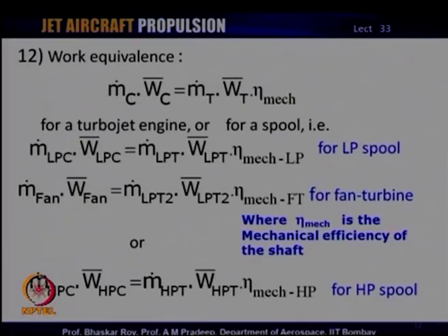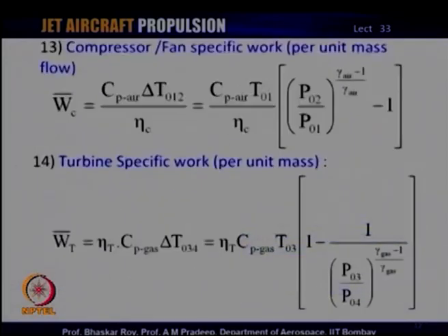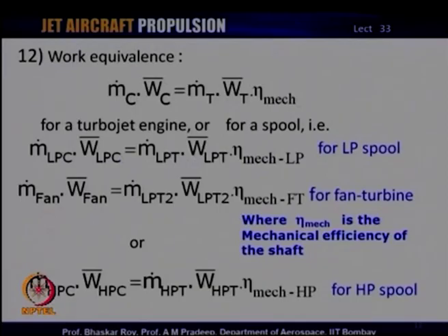Now, all the spools are having matched work between the turbine and the compressor, and we need to remember that this matching has to be done at every instant of the working of the engine. At every instant, all these spools must have matched work between the compressor and the turbine.